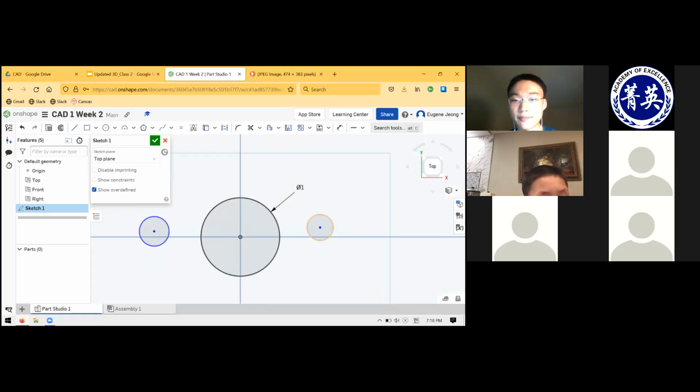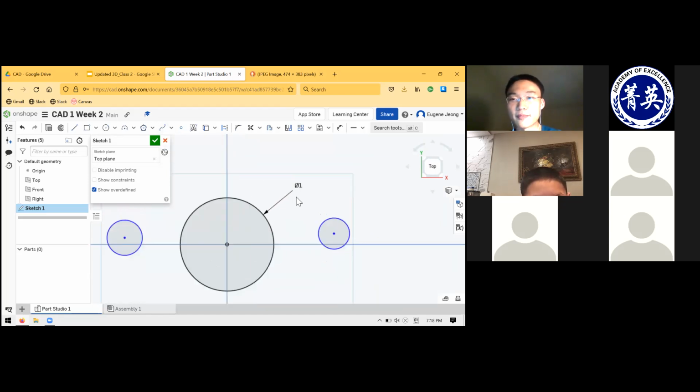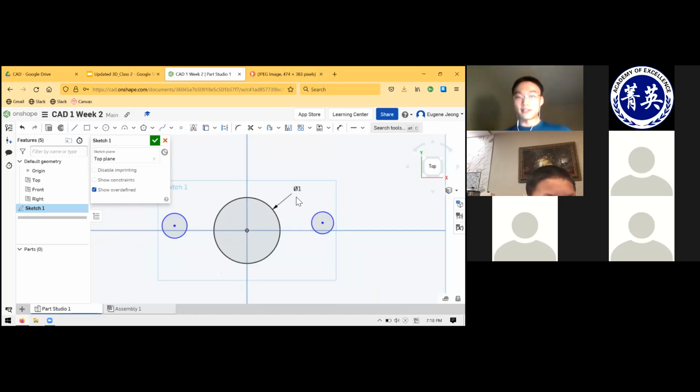What I'm talking about is how do you make the spline tool stop? Are you talking about this one? Yeah. Because when I try to click out of it to stop it, it just creates another point. Right. The spline tool I'd recommend not using at this point unless you feel very confident about how to dimension or fully constrain things, because as you are probably discovering, the spline tool gets very messy and it becomes very difficult to fully constrain, just because each spline has a number of different parameters.